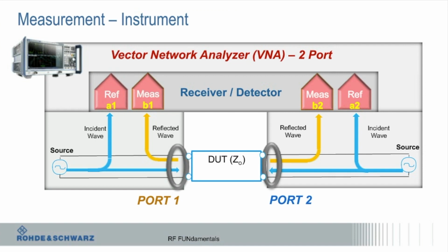Did anybody here use a VNA? Okay, good, lots of hands. Good answer. My people. Anyway, in the olden days, if you have enough gray hairs, when you did that calibration, you had a little box with little metal things that you would screw in and out. It would say, connect this one, connect this one, connect them together, blah, blah, blah. It took a lot of time. You got things stuck in your finger from doing it so many times. I have SMA fingers. And it was fairly error-prone. You had to be really careful because if you connected the wrong one or pushed the wrong button, obviously it would give you an erroneous result.